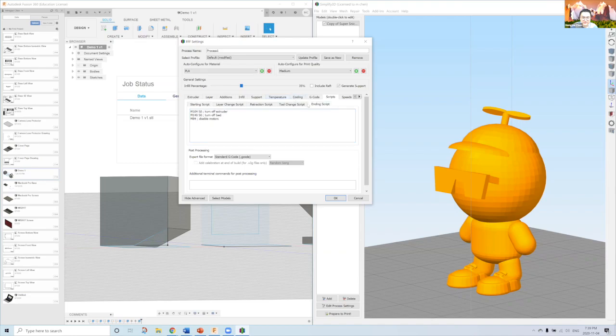At the very end, it turns off the extruder, turns off the bed, and disables all the motors. What that does is it stops the heating from continuing. That saves you power, it prevents the burning of material, and it also helps protect your 3D printer mechanisms from overexertion.